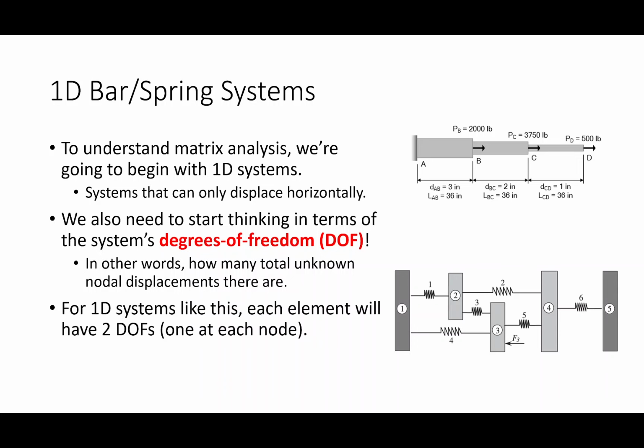And so I'm calling this a nodal displacement, I'm calling this a 1D problem because I'm assuming for each joint that there is only one displacement, okay? And I'm only talking about displacements in the x direction. So while this probably looks scary, I think what you're going to find is that this is actually a lot easier than you would think. And this and this problem really aren't that much different. Now, whether we're dealing with a spring that has some spring constant K, or we're dealing with a bar that has some length L, and this has some E and some A, the problem's going to be handled the same way.